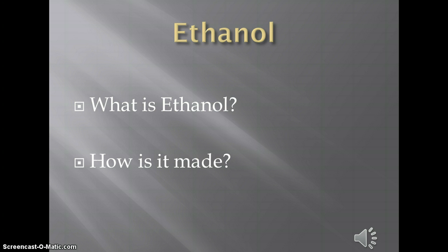Recently constructed ethanol plants use a dry milling process that begins with grinding the corn's kernels into flour or meal, and then slurrying with water to form a mash. A high-temperature cooker controls the mash's bacteria. Once the mash is cooled, yeast is added to begin the fermentation process that converts the sugar into ethanol. A conventional distilling process then concentrates the ethanol to 190 proof.